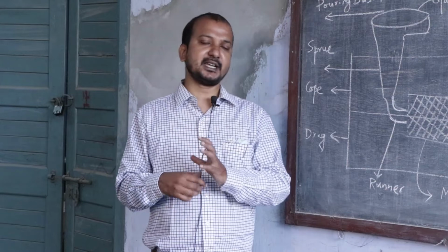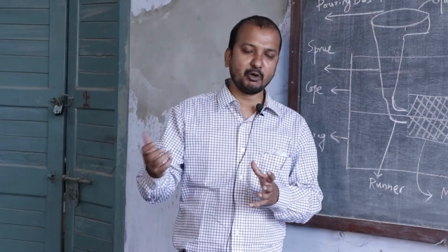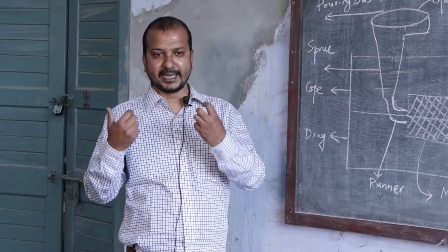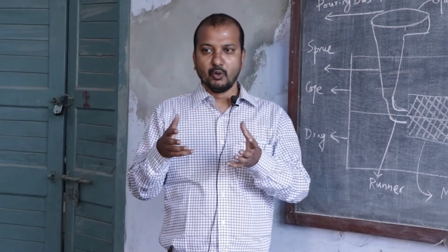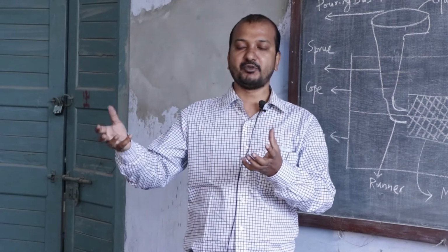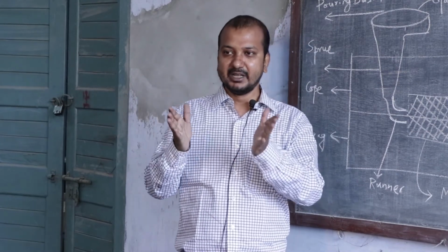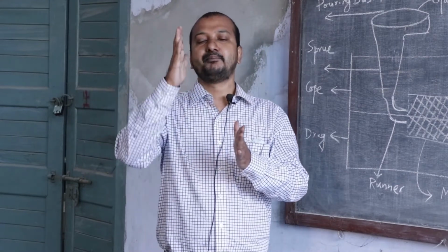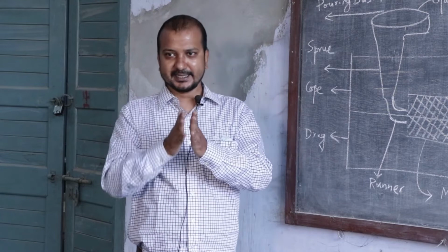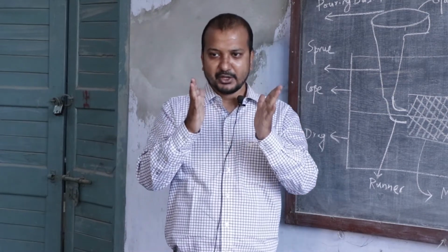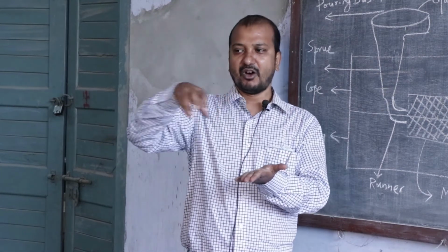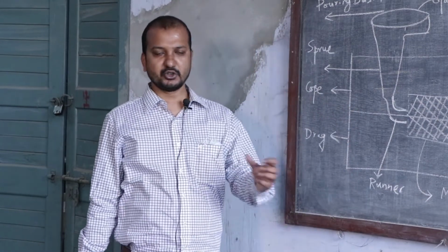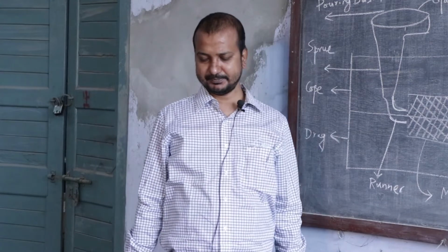After the solidification of the job, we will have to take it out from the mold cavity. So that we can withdraw it from the mold cavity easily, some draft will be provided. If the surface of the pattern is a plain surface, we will give some taper so that it can be withdrawn from the mold cavity easily. And there is also distortion allowance and ramming allowance.